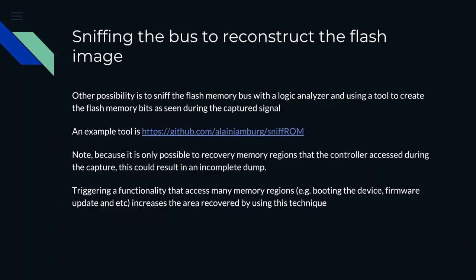Another way to recover the contents of the flash is to use a logic analyzer, keep sniffing that connection, capture all the commands, and use a tool that is able to recreate the content of the flash itself.